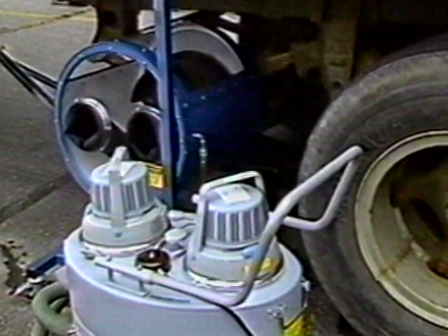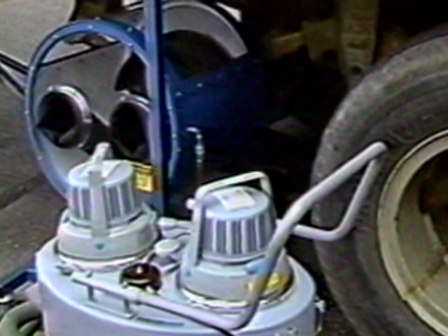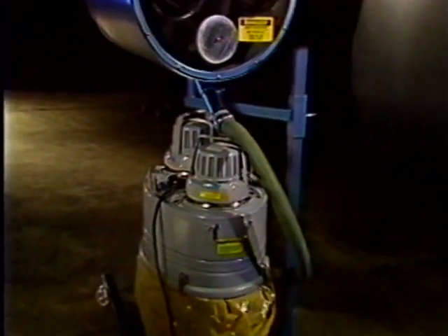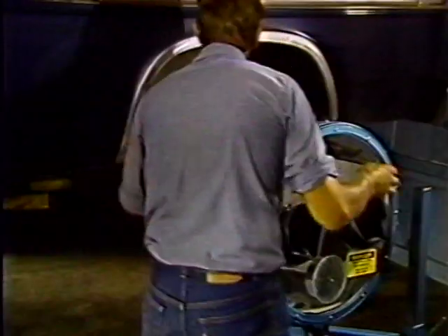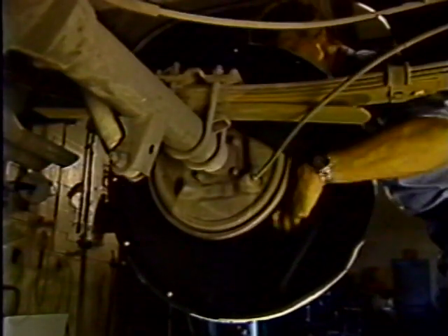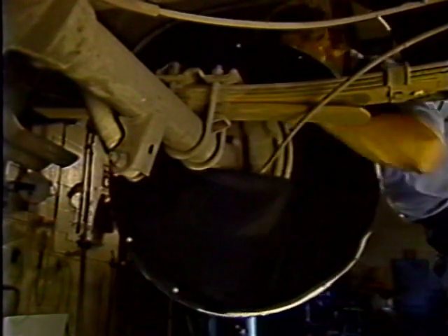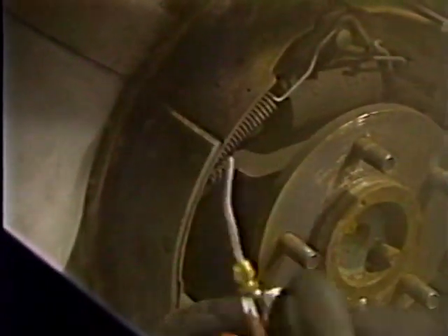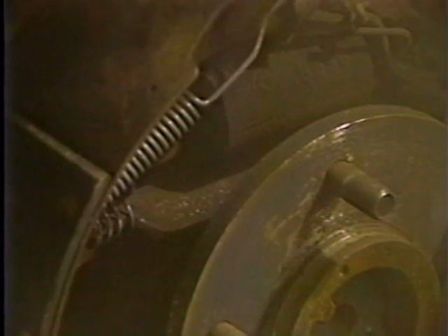Various vacuum systems are manufactured. Follow the instructions provided with the specific piece of equipment. Generally, to use a brake vacuum system, mount it over the brake assembly. A large rubber diaphragm fits around the backing plate. Insert your hands through the enclosed rubber gloves, then use the air nozzle to blow dust off of the assembly. The vacuum system will then pull the dangerous asbestos dust down into a storage container.